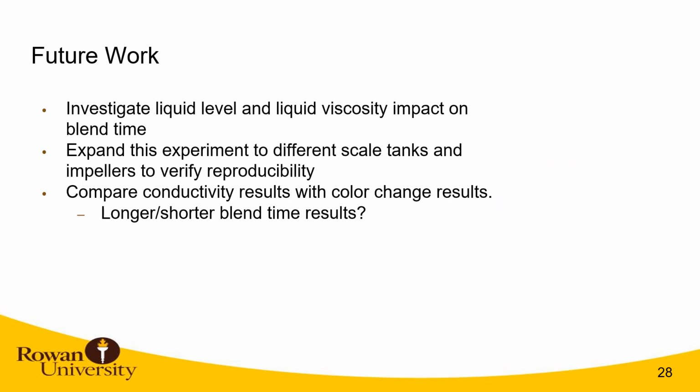So some of the work we want to do in the future involves investigating the liquid level and the liquid viscosity and seeing if that has any effect on the blend time in the same tank that we're using. In addition, we want to expand the experiment to different scale tanks and possibly a baffled tank, compare that to an unbaffled tank, and use the other impellers we have available to us and see how that compares to our already completed data. We also want to compare the conductivity results with the color change results and see if the results match or how they differ.